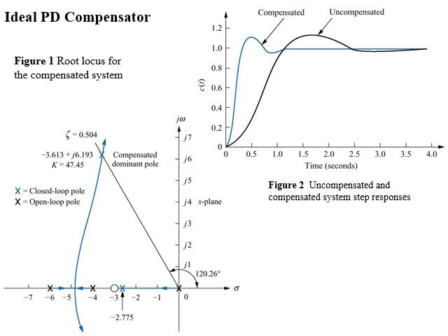Dear students, figure 1 represents the complete root locus for the compensated system, which has percent overshoot equal to that of the uncompensated one, but its settling time is reduced 3 times compared to the uncompensated one. This can also be observed in figure 2, which represents the step response for both compensated and uncompensated systems. You can observe a clear difference in the speed of response. The compensated system quickly stabilizes and enters the steady state, whereas the uncompensated system takes much more time.